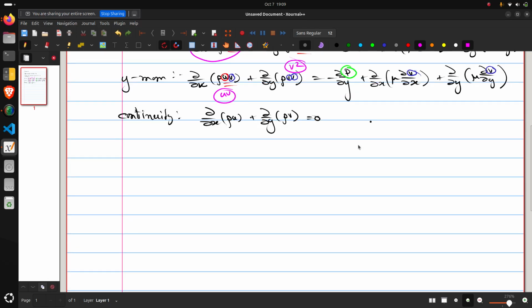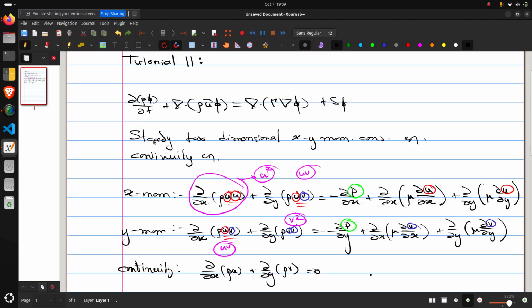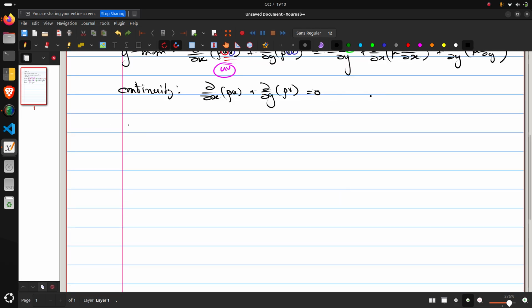Okay, so for example, if the pressure gradient is known, the way to obtain the discretized equation is very similar to what we have done for the GST equation, I mean the general scalar transport equation, in those steady and unsteady convection-diffusion equations. The solution methodology will be similar if we have the pressure gradients known, right? But in a general purpose flow, while computing the flow field, we also require the pressure field as well. This is also a part of the solution. So the gradient of pressure is not known beforehand, right?